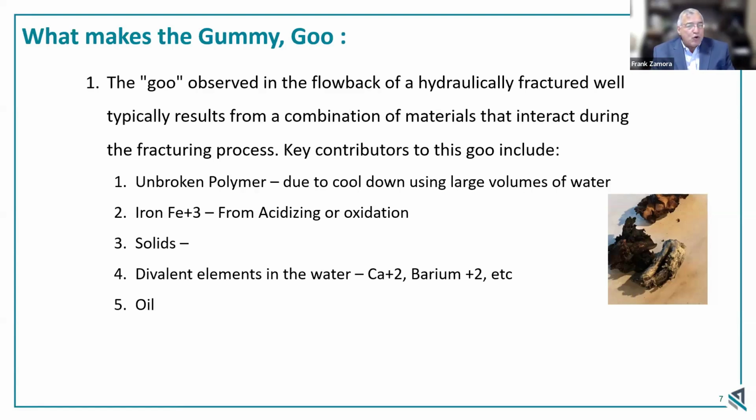So if we were to do a cool down or a heat up type program in a low bottom hole temperature well after pumping millions of gallons of fluid, we would probably see that it takes several days to get back to 140 degrees, or at least to 130 degrees where the breaker can actually kick in. But by then it may be too late. It may have already come in contact with the ferric iron, and it may have caused some of this agglomeration, which makes it a little more difficult for the oxidizer to break.